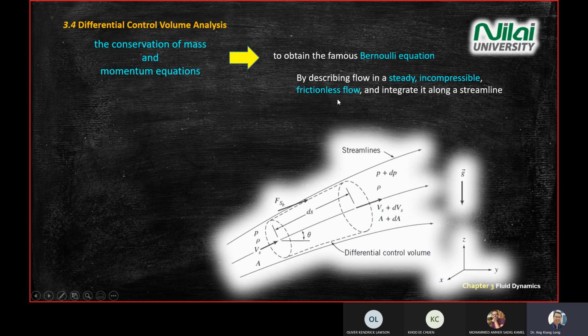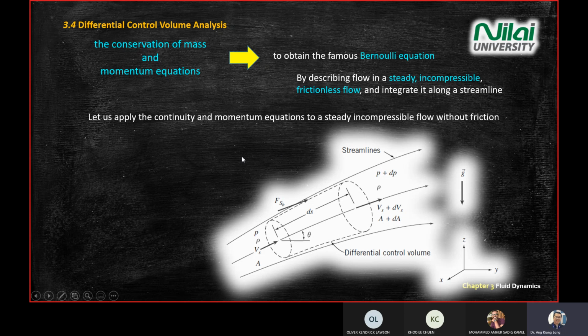You can write that we assume for the Bernoulli equation that our apparatus does not have friction inside the flow. And also we assume it's incompressible and we have a steady flow. So we have to write all these errors inside the report. Okay. So again, we start with steady flow, incompressible, and frictionless condition.